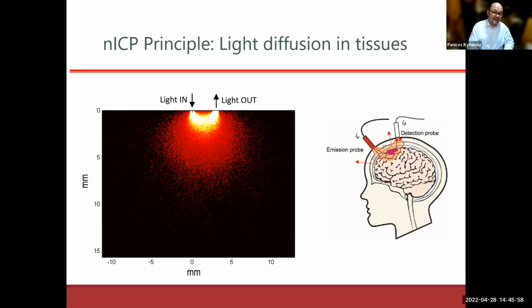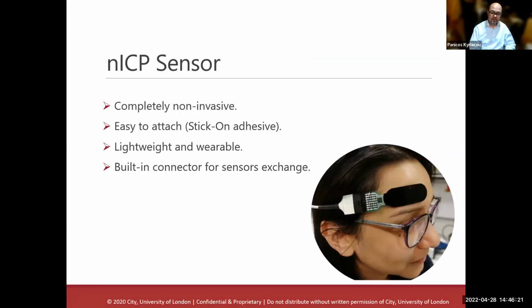Since we have this confidence that light can penetrate into the brain, we thought, well, can we actually look at the pulsations of the PPG coming back? Because primarily, or exclusively I should say, NIRS utilizes the DC component, or the whole absorbance of the signal, in order to work. So for us, we developed a completely reflectance optical sensor, and you can see here one of our researchers wearing the sensor. It's almost like a peel and stick, comprises 4 wavelengths and 2 photodiodes, very lightweight.